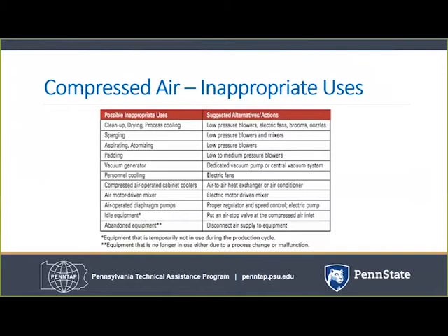Since compressed air is valuable, make sure you only use it in applications that work most efficiently with compressed air. This table provides examples of inefficient uses of compressed air, along with alternatives that are effective and efficient. Walk through your plant and identify all compressed air uses and, if possible, the flow and pressure requirements of each use.